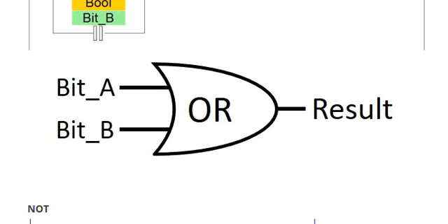Now we will try to see OR gate. We know in OR logic, if one of the inputs is true, then the result will be true. The same thing we are implementing using ladder logic. Here we have to understand that when we say OR logic, we have to implement the circuit in parallel mode. Hence we have connected two NO switches in parallel operation. If one of them becomes true, then the output will become true.